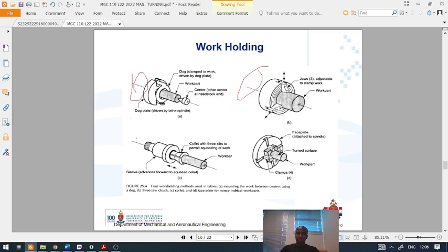The other one, you use a collet. This is the spindle side, this is the spindle. This you can attach to the machine and remove it depending on which one you want to use. For the jaw chuck, these jaws can be linked, so they will move at the same rate going in and out, same position. Therefore, when they touch the circular component over here, they will also be touching with the same force, same position. Even on the one at the back, the chuck will have a screw to force this to close up.